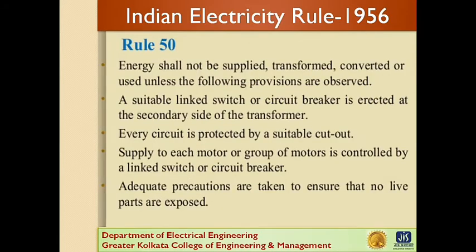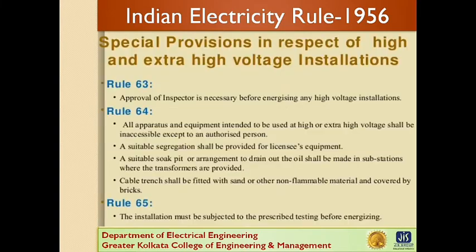Rule 50. Energy shall not be supplied, transferred, converted or used unless the following provisions are observed. A suitable linked switch or circuit breaker is erected at the secondary side of the transformer. Every circuit is protected by a suitable cutout. Supply to each motor or group of motors is controlled by a linked switch or circuit breaker. Adequate precautions are taken to ensure that no live parts are exposed.